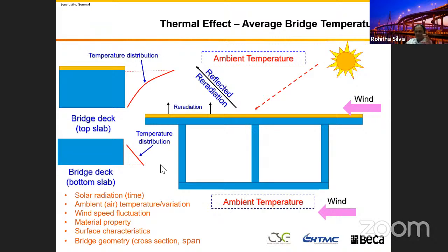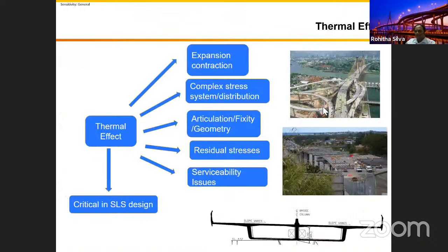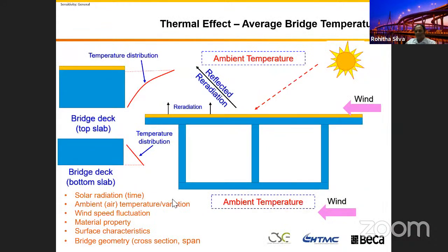Is it clear why we get this? Now you can understand why we are going to get the complex residual stress within the bridge cross section. When you are designing a continuous span bridge like that, that residual stress distribution has a significant impact when you design for the serviceability limit state. That is very different from designing a straight bridge sitting on elastomeric bearings. Yeah, it's very different.